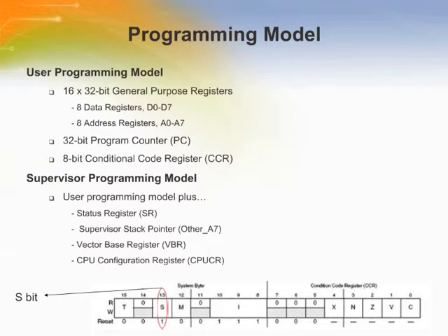The supervisor programming model includes all of the user registers plus a status register, another stack pointer, a vector base register used during exception processing, and a CPU configuration register, which provides software control of hardware configuration settings.